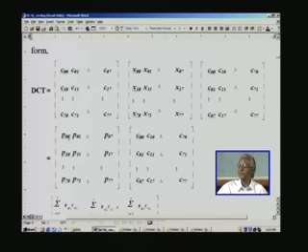And once it is done, we repeat the same thing, retain the same row, but change the column now, second column, and get P01, and so on for 8 clock cycles. You would have got the entire row of this, and we term this a partial product here. And once this row is complete, we can start multiplying the second one. So we repeat the same multiplication here.